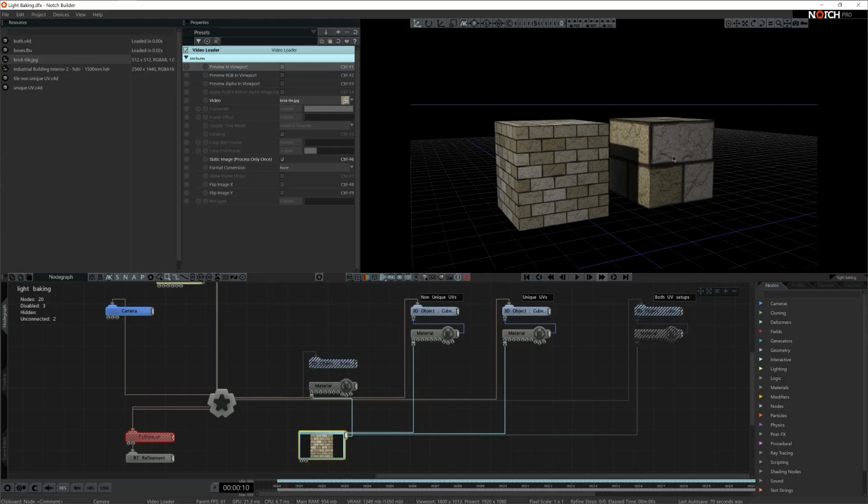Well, since every single facet here is unique, if we're dropping a light on the model and a shadow is being dropped on one of the facets, this shadow will be baked into this specific location of this specific facet. And that is because this wall has a unique coordinate for texture mapping. Now, if we were to do the very same thing on this cube with the tiled texture sheet, the baked lighting would just not work out because the very same baked lighting would be applied on every single wall equally, and that would look just plain weird.